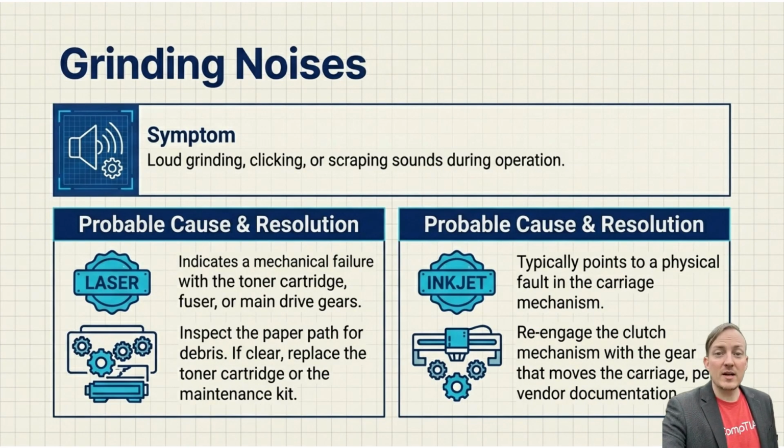What if you hear grinding noises? Loud grinding, clicking, or scraping sounds during operation are serious red flags. In a laser printer, this indicates a mechanical failure with the toner cartridge, fuser, or main drive gears. Inspect the paper path for debris, and if clear, replace the toner cartridge or the maintenance kit.